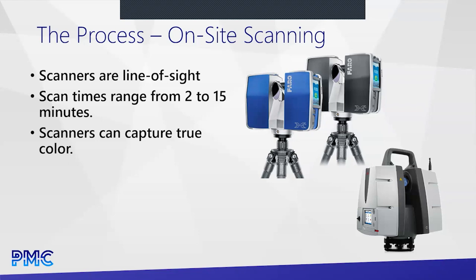There's also mobile scanning and photogrammetry, both of which are gaining traction but are not as common. In general, you could expect on a traditional scanner to capture maybe up to 20,000 square feet a day on site, depending on the complexity of the site. With mobile, that number could be over 100,000 square feet a day. That gives you a ballpark idea of how long we'd be at the site.